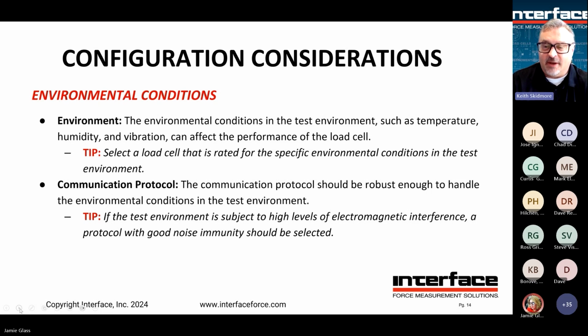Another thing, in temperature, for tests that have extreme temperature ranges, sometimes the load cells can be rated for very extreme temperature ranges, but the digital instrumentation attached to them may be the limiting factor. Say you have an inline or integrated amplifier, that amplifier may have a smaller allowable temperature range than the load cell. That can be okay if it's still within the requirement, or it might be necessary to locate the actual amplifier outside of the test chamber and digitize outside of the oven or outside of the freezer or whatever. So those are things to keep in mind.